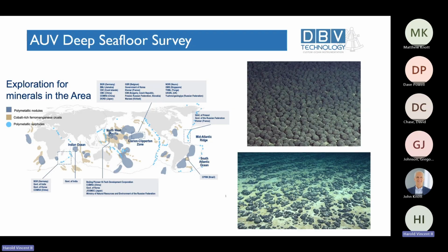So in this type of a scenario, you would put transponders down, either several transponders and do long baseline acoustic positioning, or single transponders and do USBL acoustic positioning, but you would periodically get acoustic positions that you would feed into the AUV's inertial navigation system, so you get the level of accuracy needed for mapping this area prior to an exploitation phase where you start the harvesting operation.